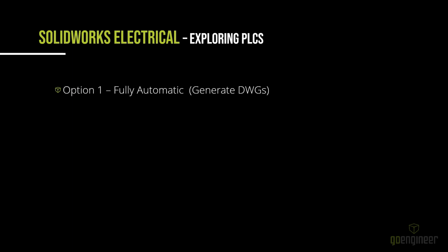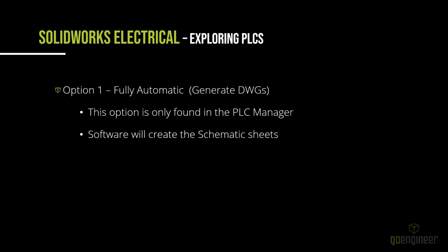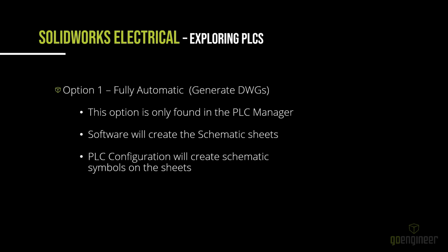The first option, again, I call it fully automatic, but it is called Generate Drawings. This option is only found in the PLC Manager. The software is going to create schematic sheets for you. You don't have to go to the book and right-click and say New Schematic and then find a symbol in the library. You don't have to do that. The PLC configuration is going to create a schematic symbol on each of the sheets for you.